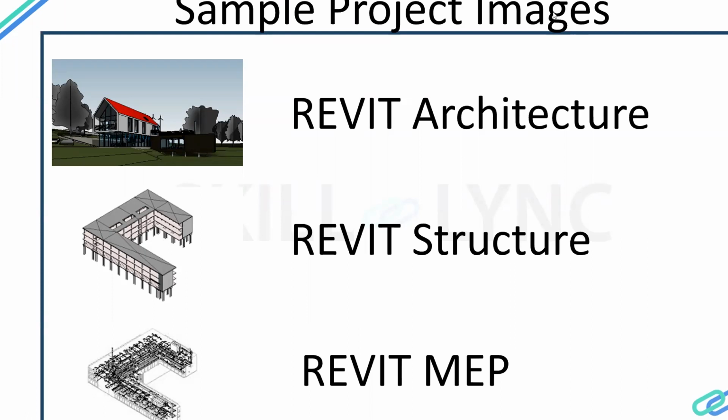Once I prepare the template, I just pass it to my team. For example, I have an individual mechanical team, so I pass the file to the team. They use the template and then they prepare the model. So my team doesn't need to worry about the standards, because I prepared the template based on the standards. If they take the duct of a supply diffuser, it should be in blue color only, so no need to worry about the color code. If they take the text, it should be Times New Roman 20 mm. It's already prepared in the template.